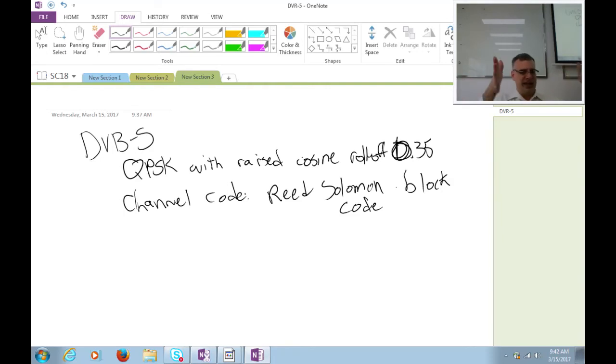And so you're taking a hit on the actual transmission rate because you have to feed these modulation schemes at whatever rate they're designed for. And therefore you're effectively shrinking your real data rate in order to make the data that you actually do transmit more reliable. The other type of code other than a block code is a convolutional code, which is basically